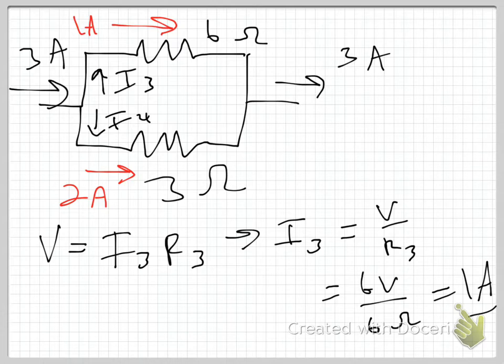If I form the ratio of these resistors, I get 1/2, 3 ohms over the 6 ohms, which is the inverse of the ratio of the currents flowing through them. Of course, you can show that mathematically, but that's not an accident, right? The amount of resistance determines the amount of current in a very mathematical, proportional way.